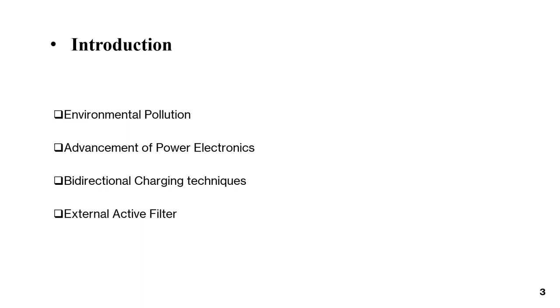A number of operating modes were developed as a result of the power flow, including G2V, grid to vehicle, which allows battery charging directly from the grid, and V2G, which is vehicle to grid, which permits battery discharge to the grid, and finally the ability for the vehicle to operate while the battery is supplying electricity to the home. Because the bidirectional charger is not actively charging in this mode, it is uncertain if it can function as an active shunt power filter while the battery powers the home.